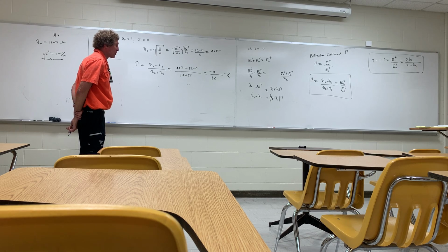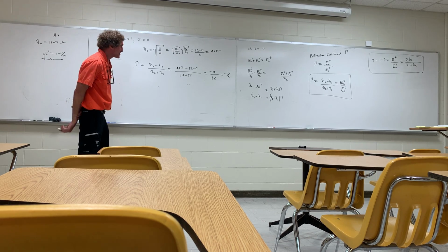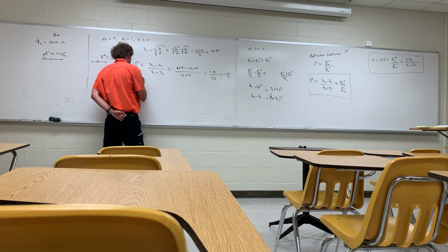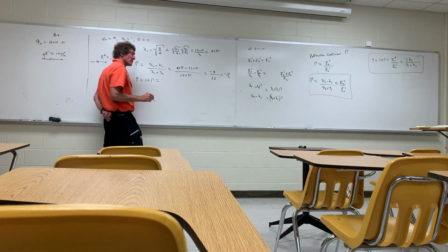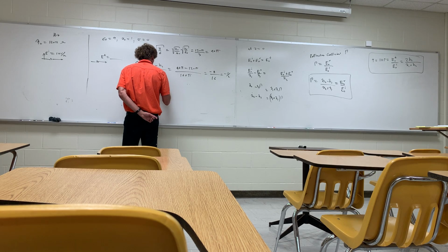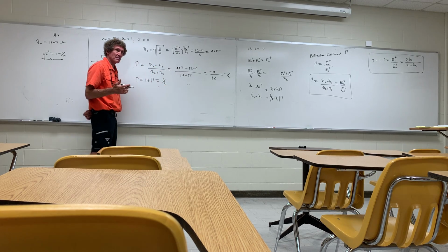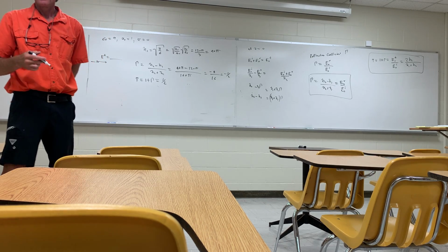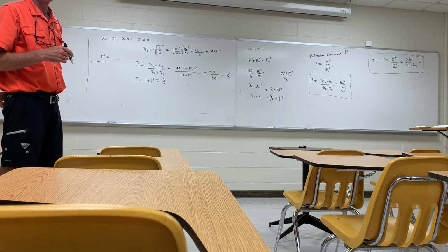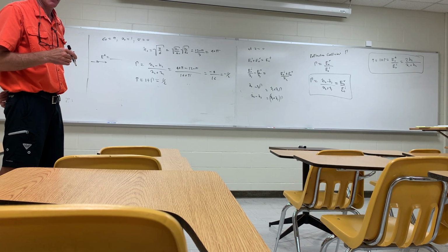All right. What, by looking at this, is the transmission coefficient? 1 plus the reflection coefficient, or 1/2. Do you agree with that? Right. It has to be, correct. Just add 1 plus minus 1/2 is plus 1/2, correct, class?